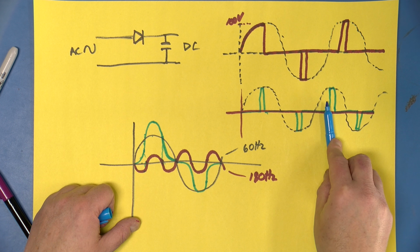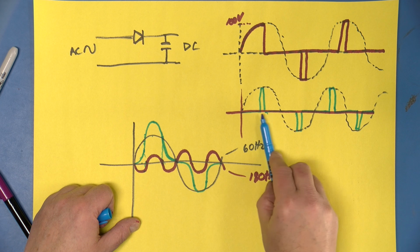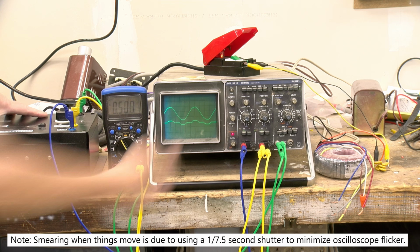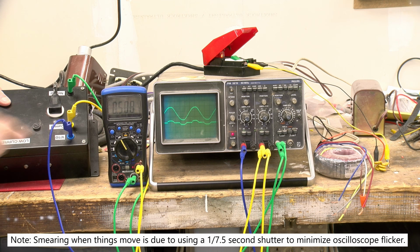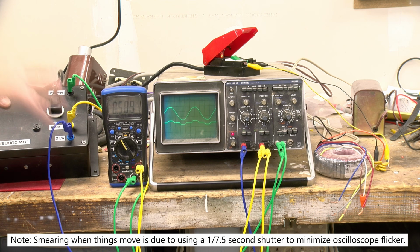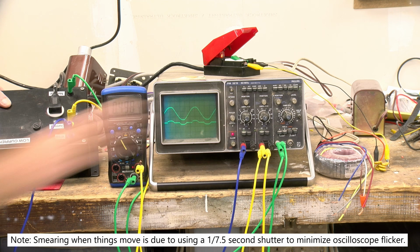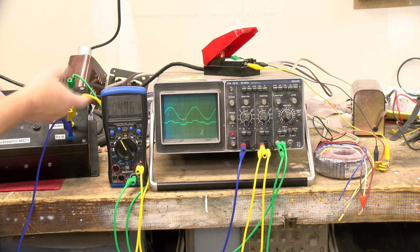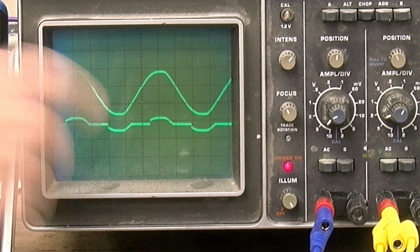So, enough of theory. Let's look at some real things, and you're going to be astonished how terrible some of these currents actually are. So to look at power factor on the scope, I have this box that I built a while ago hooked into the circuit, and what it does is it gives us a measure of the line voltage going onto one channel of the scope, and it gives us a measure of the current converted into voltage going into the other channel on the scope, the lower channel.